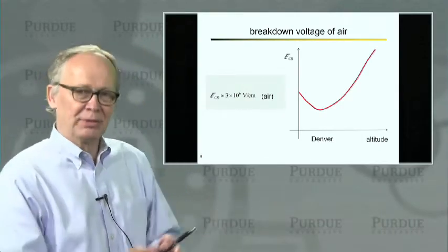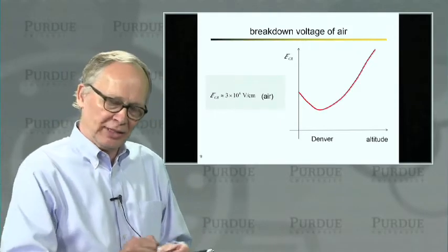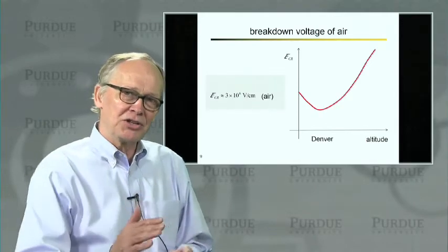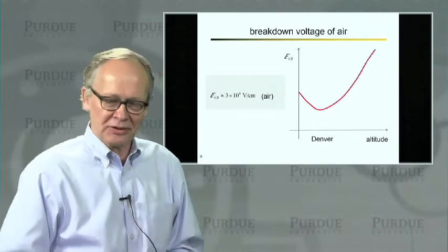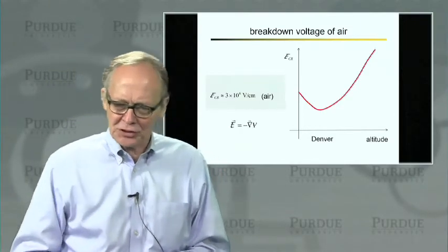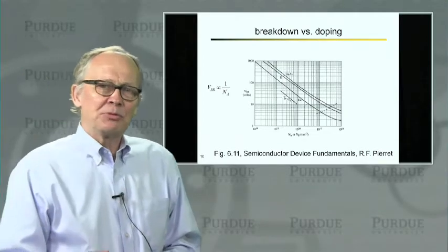We looked at the other place. There was a sharp corner there too. Took out the file, smoothed it out. And by doing that, we could smooth out all of the sharp edges in the metal electrodes, and eventually it worked the way it was supposed to. So these curvatures are very important. All right, so that's avalanche breakdown.